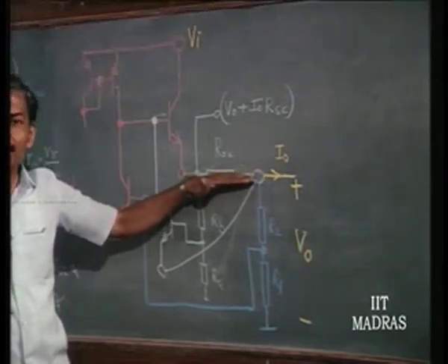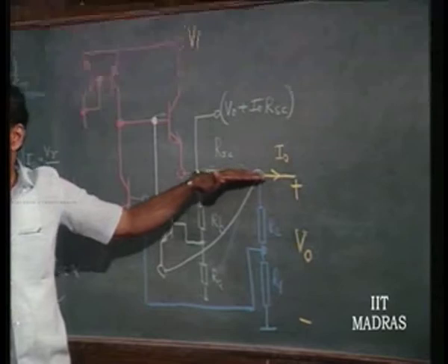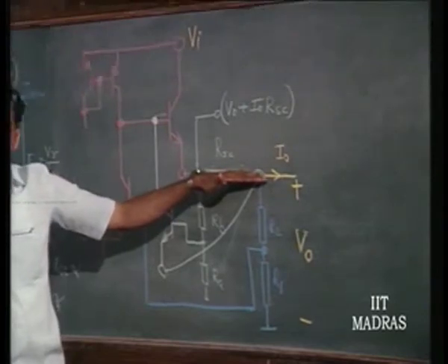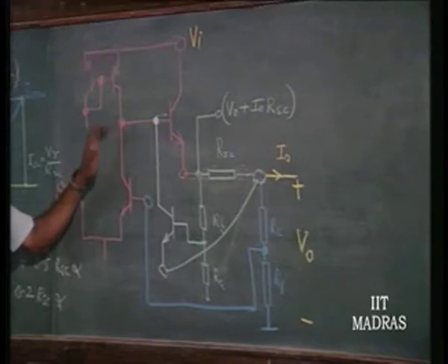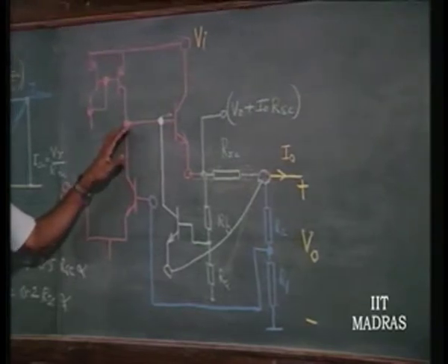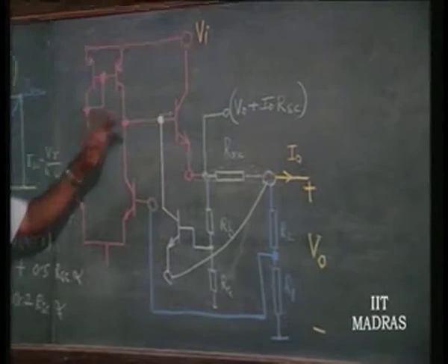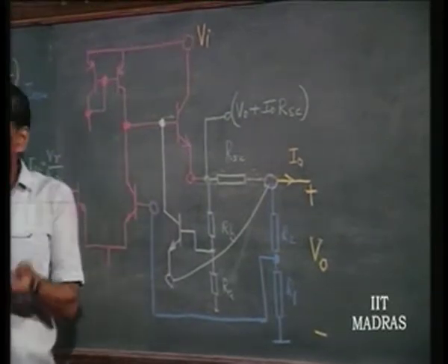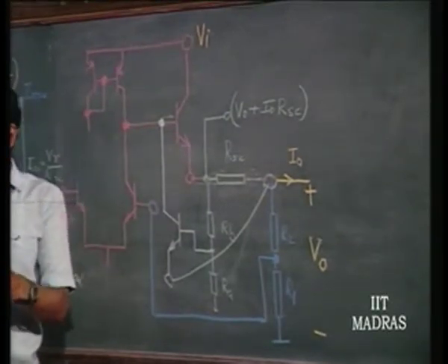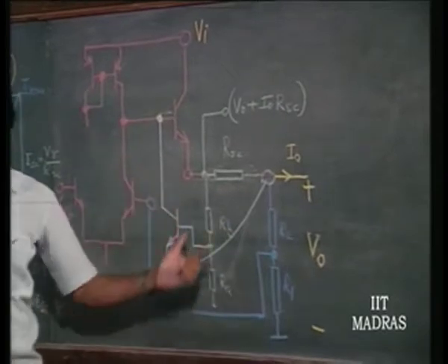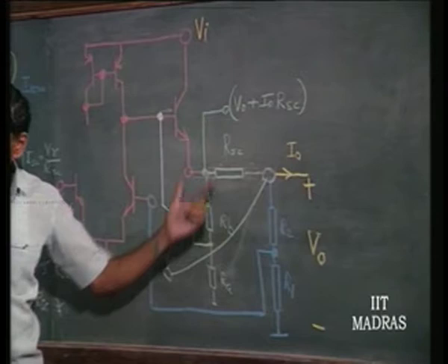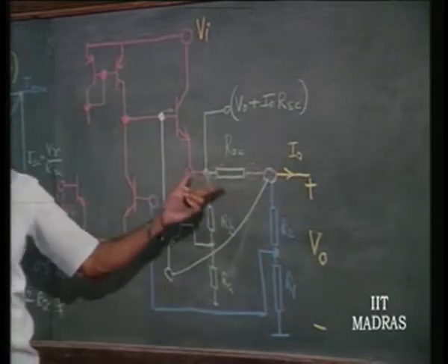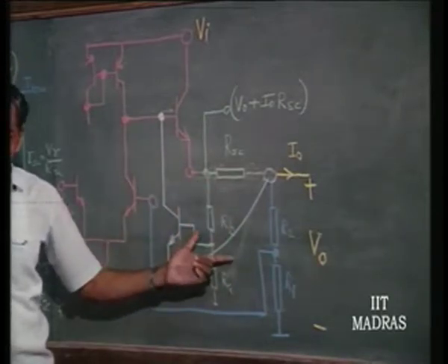Even when this is pretty high, this is not going to fix the output impedance, because we are going to make this particular thing very high, and that divided by beta is the output impedance without feedback. With feedback, it is going to be reduced by the loop gain of this stage anyway. So, that output impedance is going to be low because there is negative feedback here.